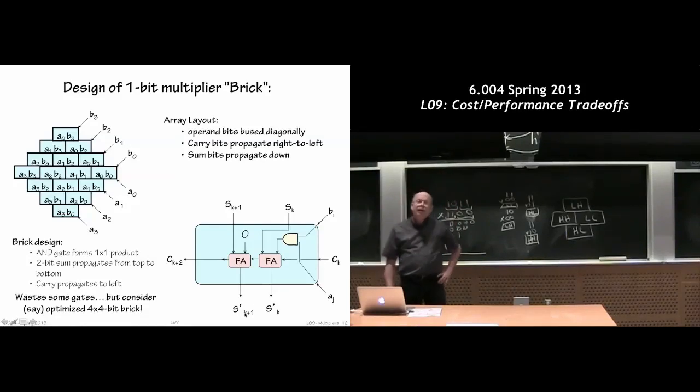And here's a little piece of circuitry involving the full adder building block. The full adder is something that you've experienced in Lab 2. It adds together 2 bits and a carry in, so 3 incoming bits, and produces a sum and a carry out. So this is our little building block, like so. This is really the only thing where you actually have to do circuit design. And now we're just going to figure out how to piece these building blocks together to form the actual resulting multiplier. This is not the most efficient thing.